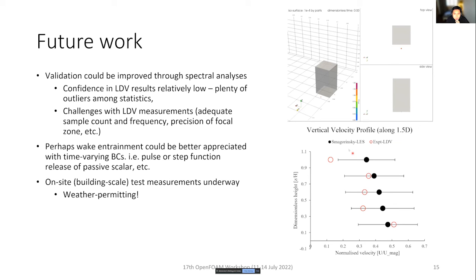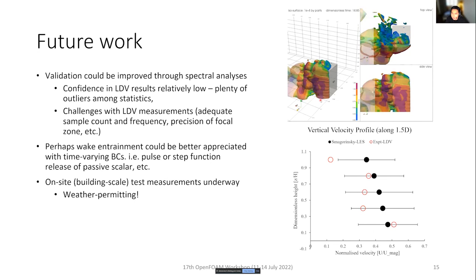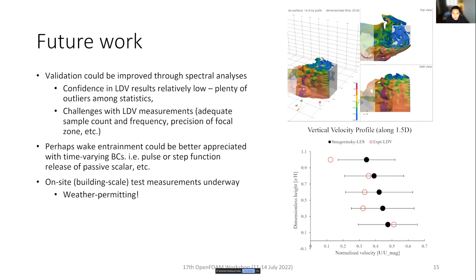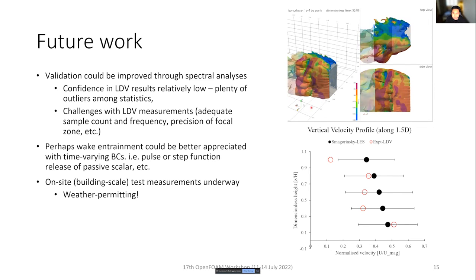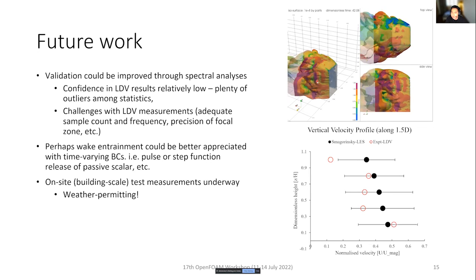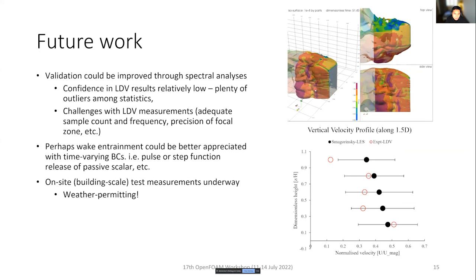Also, to better appreciate wake entrainment effects, perhaps we could implement a time-varying boundary condition. So maybe like a pulse or step function to inject, to disperse this tracer gas into the domain.